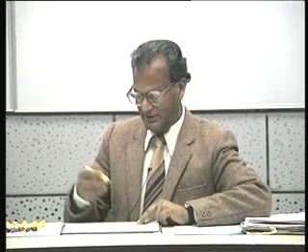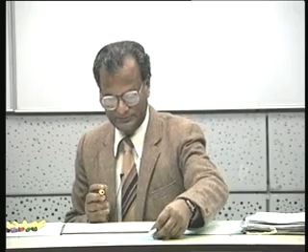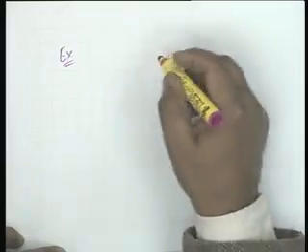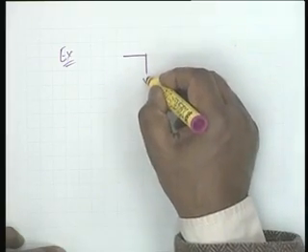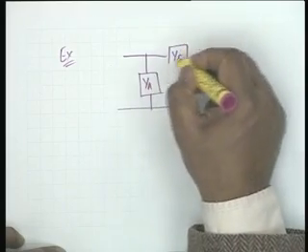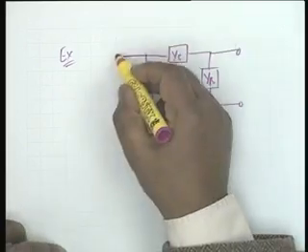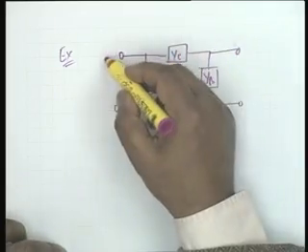As you know, the hybrid pi equivalent circuit is the most universal and the most desirable kind of equivalent circuit for a transistor, and they originate from the H parameter model of a general 2 port. Let us take an example. Suppose we take the familiar pi network YA, YC, YB. This is port 1 and port 2.